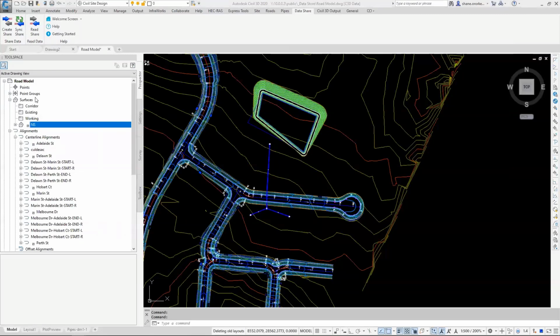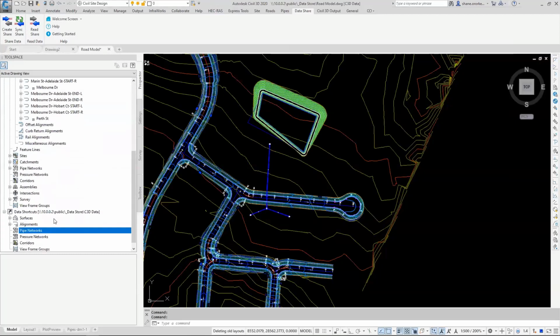So if you go and try and connect to it, Shane, if you go down the bottom to the data shortcuts, if you actually tried to click on it down there, validate. Yeah, sorry, it's validate. You should get an error. Yeah, I jumped a bit too quick, but yeah, it's validate data shortcuts. And it should find an error now because the folder has been moved fundamentally.